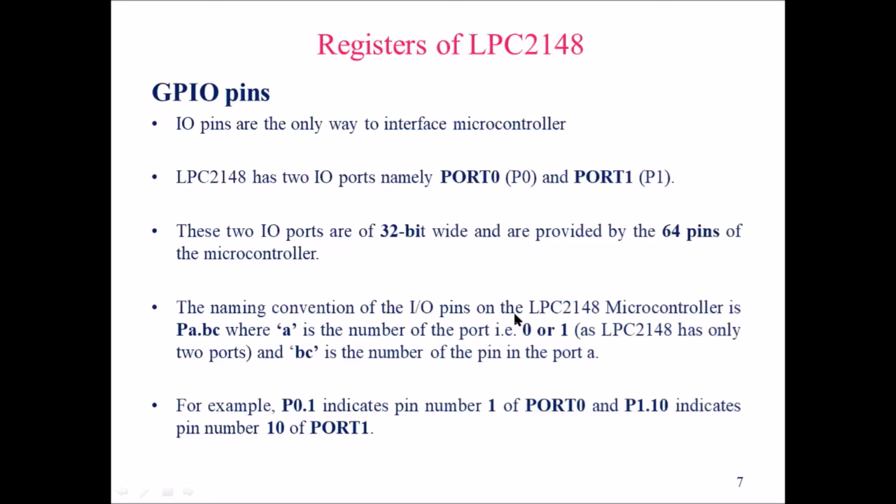The naming convention of the input output pins on the LPC2148 microcontroller is PA.BC. Here P stands for port, and A is the number of the port. As I told, there are only two ports in our microcontroller, port 0 and port 1, so A can be either 0 or 1. BC is the number of the pin in port A.